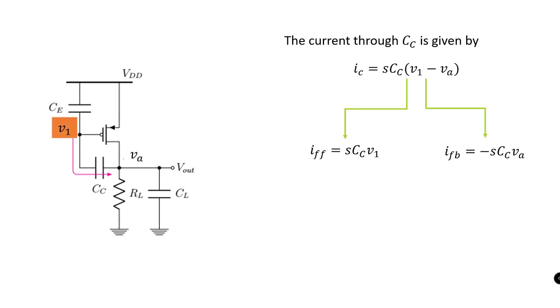Also note that when the node potential V1 is excited, it produces a small signal current at the drain of M9. When you look closer, you could observe that the feed forward current and the drain current are functions of V1, and the sum of both these currents is what defines the output current I0. And when this I0 flows through the output impedance, it results in an output voltage V0.